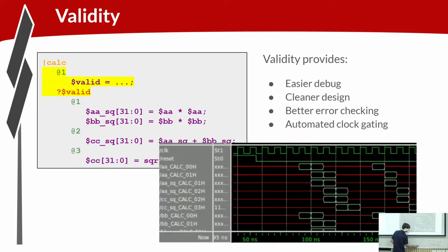It's AND gating, right? Clock gating is kind of, so yeah, you need to be careful of this, right? The clock gating logic needs to be designed so that you guarantee that the valid pulse is successfully squashing the clock pulse, right? And that's part of the clock gating methodology and the way the clock gating logic is generated. You wouldn't do it this way. You need to be able to generate the enable early so that you're successfully squashing the entire clock pulse.